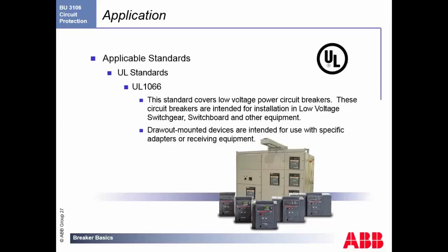Another UL standard that we are for is the UL 1066. This is power circuit breakers. Now these are really the heavy duty type breakers. They're for installation in the switchgear and switchboard. This is where you're going to have your draw out or your fixed, and it's intended to use with specific adapters or receiver.